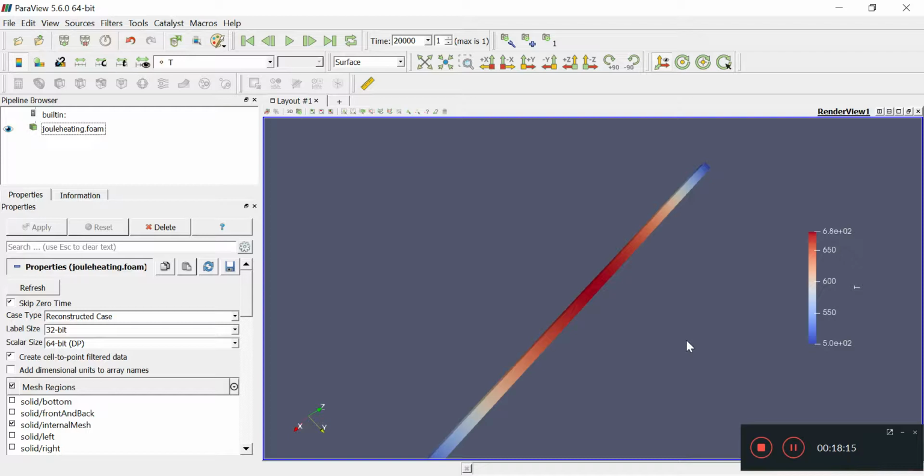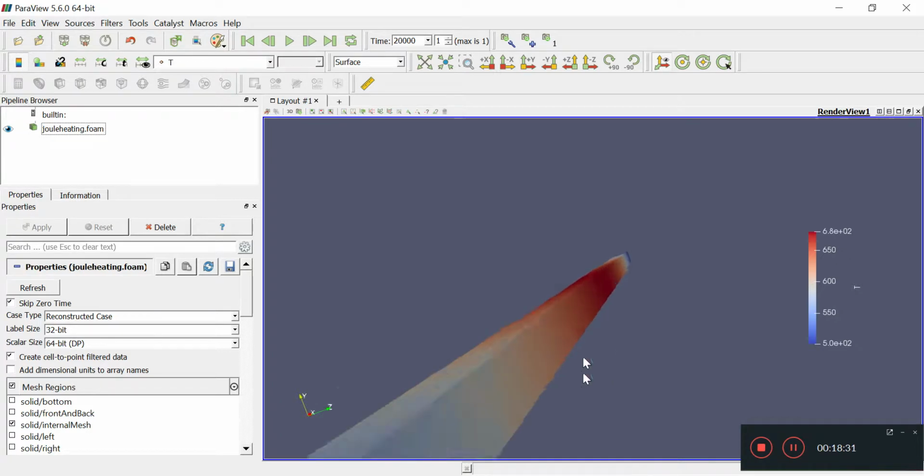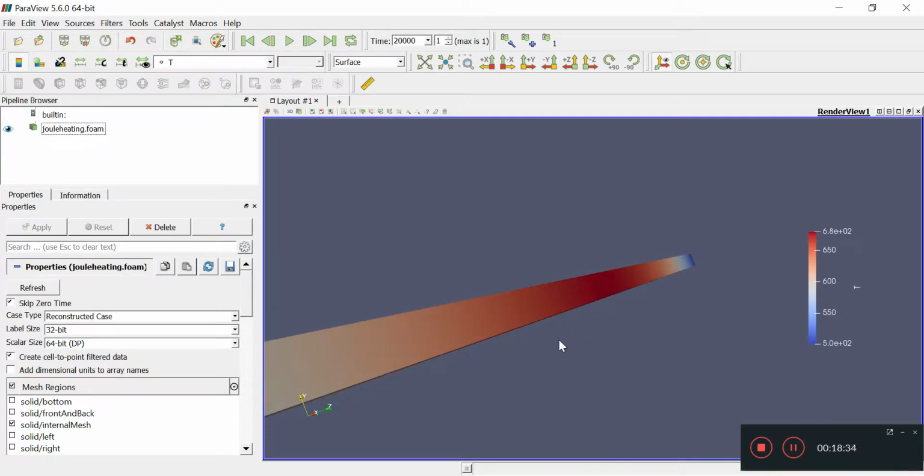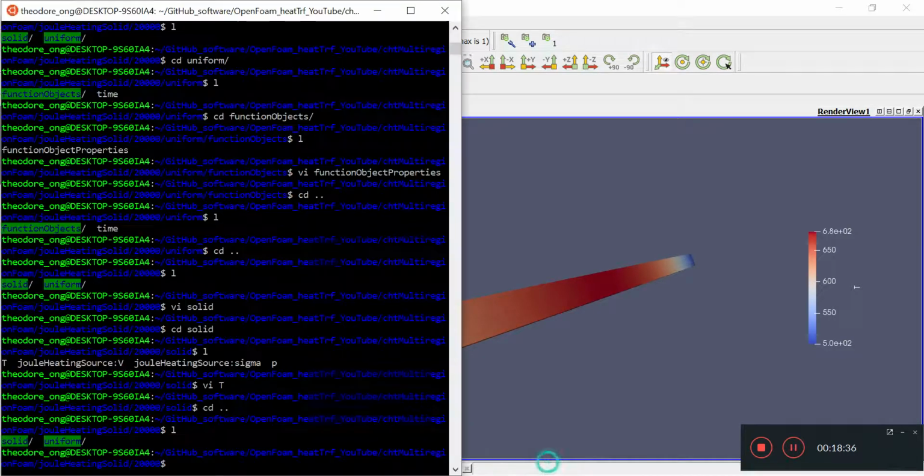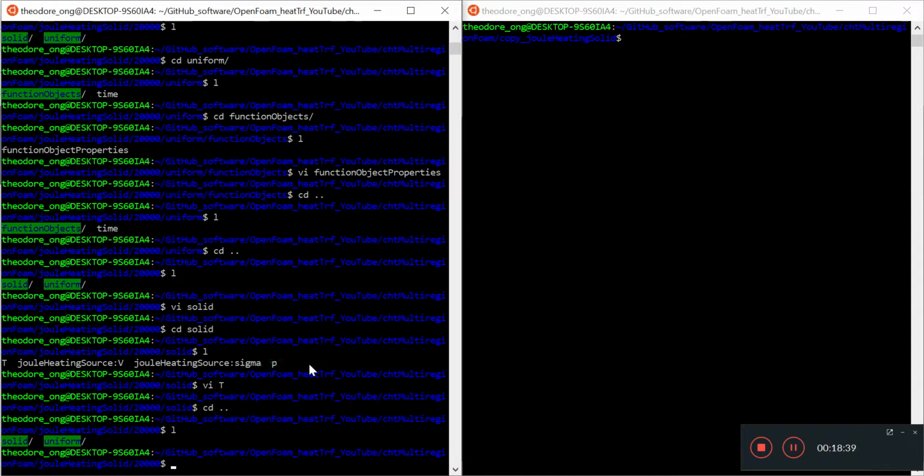And yeah, maybe the laplacianFoam does a transient simulation, but what we are going for here is steady state. So we can skip lots of that step and just obtain the steady state distribution as seen here. So probably that's why they use chtMultiRegionSimpleFoam. Not for the regions itself, but by virtue that it's a simple foam, a steady state solver for the Laplacian, the heat conduction equation.